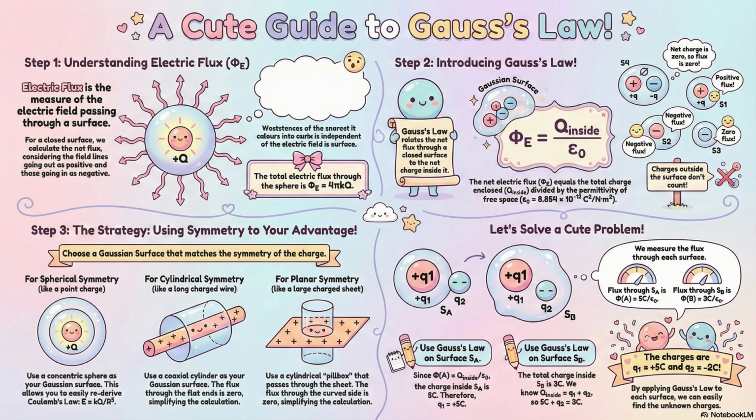Exactly. Now let's talk about the most common component on Earth. The ceramic multi-layer chip capacitor, or MLCC. The workhorse. They're durable, non-polar, low loss. But you said they have the biggest hidden flaw of all. They do. This affects the cheaper, high-capacitance Class 2 and 3 ceramics, like an X5R type. The datasheet might say it's 10 microfarads, but its actual performance is hugely dependent on the DC bias voltage you apply to it. So if I buy that 10 microfarad cap and I run it close to its rated 10-volt limit, what am I actually left with? You could be left with 80 or even 90% less capacitance than what's on the label.